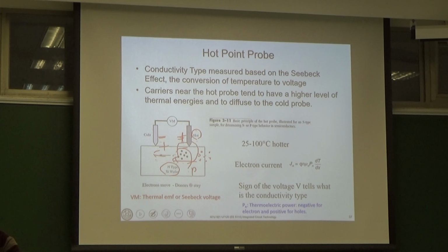In this case, we know the conducting carriers are holes, so this is a P-type wafer. That's the basic principle of the hot probe method.